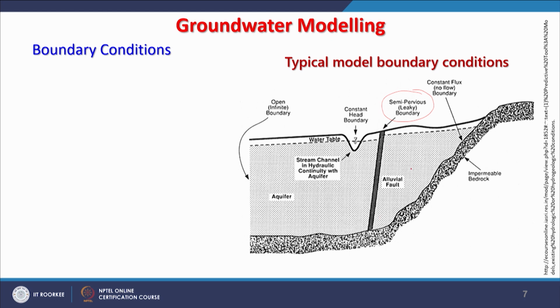Though it is an alluvium fault, in the Indo-Gangetic plain similar situations can be found at many places. Within the alluvial plain we also have faults, and these faults may have impervious deposits, meaning clay rich sediments, because of the faulting. So, that becomes a boundary, which will not allow flow of water from one end to another through it. That is one type of boundary.